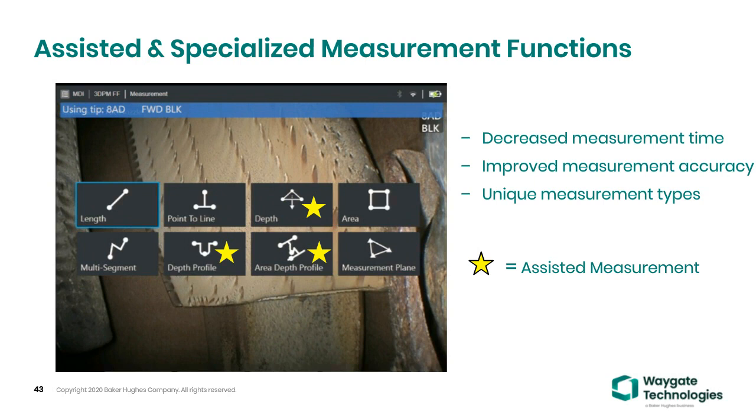For the traditional depth measurement, after you create a reference plane by creating 3 cursors, the MVIQ will automatically place the 4th cursor at a point which is either at a maximum height or minimum depth from the established plane you created with those 3 cursors in the vicinity of those 3 cursors.